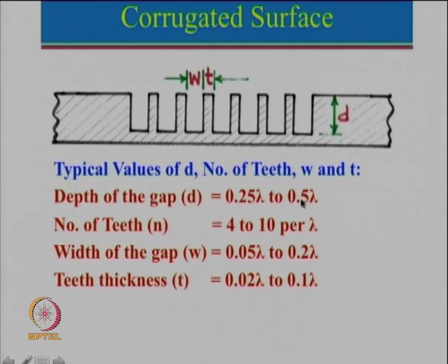If it is 0.5 lambda, the short here will act as a short, which means there will be no attenuation at all. And if 0.25 lambda is there, then the short here will act as an open over here, which means a larger attenuation. As we saw in the previous example, they started with 0.5 lambda and then went on to make it 0.25 lambda.